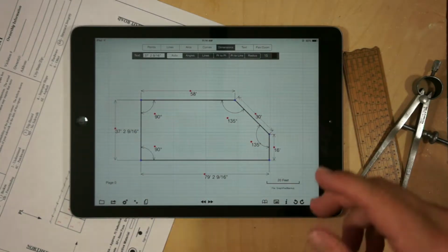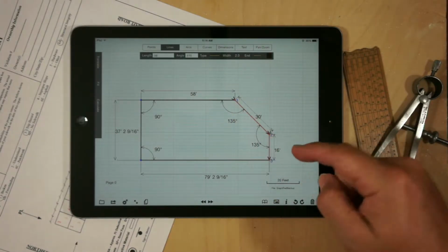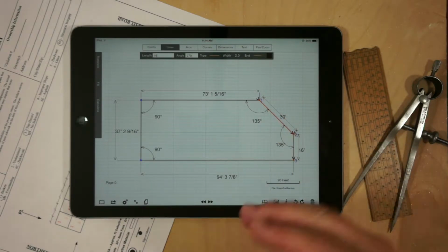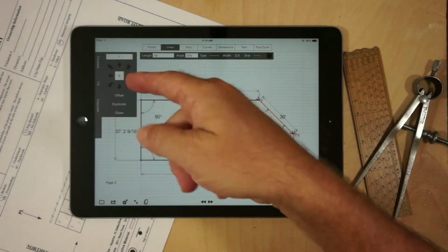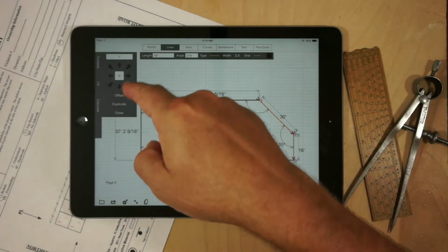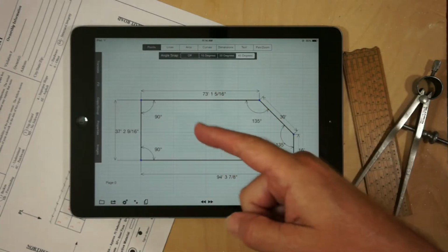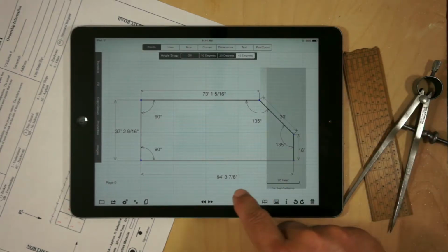Now, to manipulate the geometry, we can go into Lines mode, select a couple of lines, and drag them, and we'll notice the dimensions automatically update. If we need precise translation, we can go into Translate, and then we can type in the value and the direction and hit Offset. Another way of changing our geometry is to go into Points mode, creating a selection area,